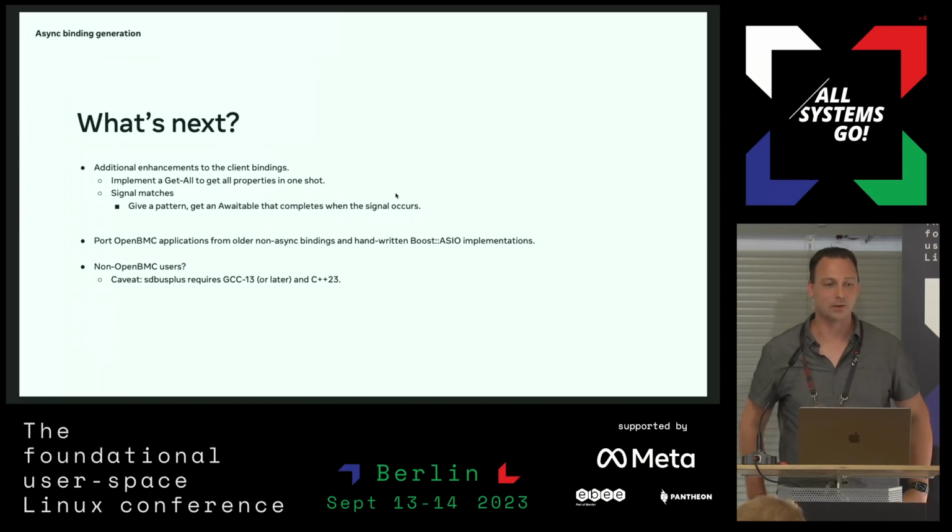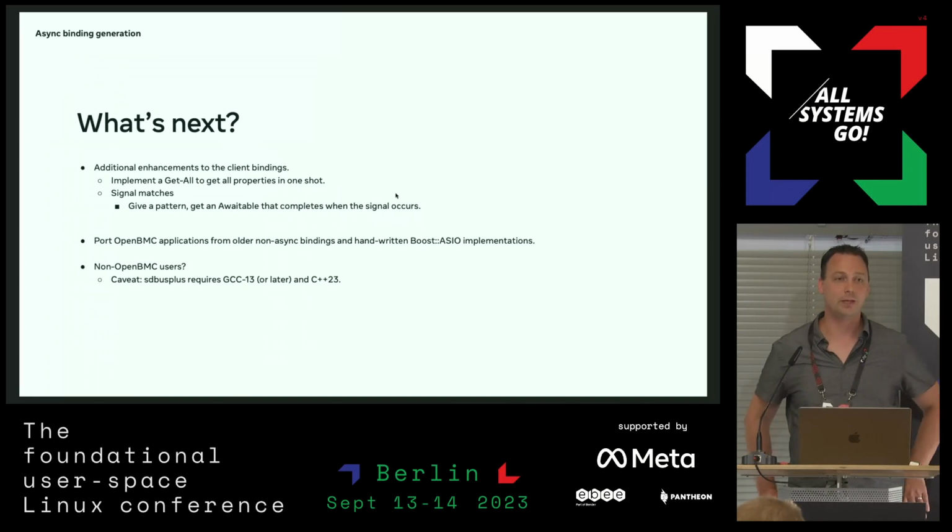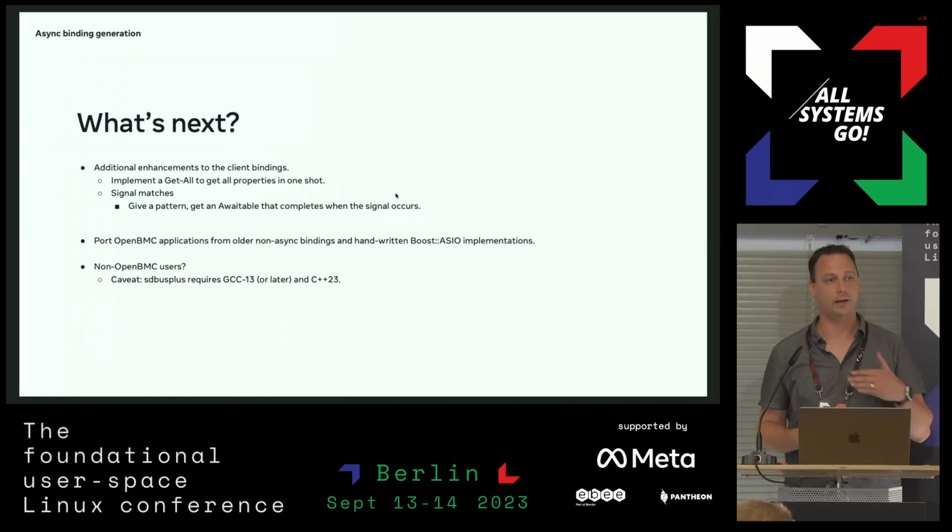Yeah, great question. Generally, BMCs do not have real-time requirements. If you have real-time requirements, in most servers there'll be CPLDs or particular dedicated hardware to deal with them. An example I've seen in a pretty common server design is that there's a watchdog within the BMC, and that emits a heartbeat signal.